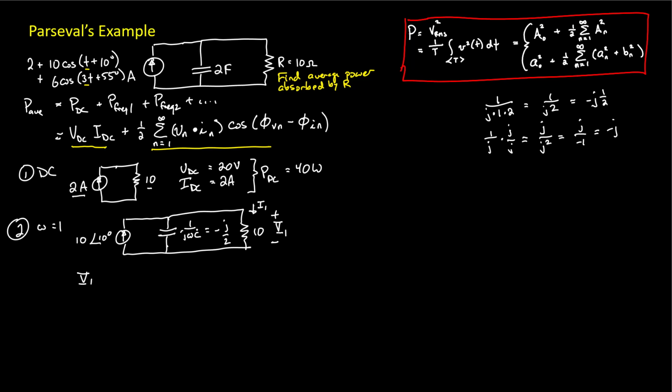Of course, that would give us I as a result, and we're really looking for V. We could do a nodal. We'd have, put ground down below, one equation, one unknown. I think it's even easier, though, to say that the voltage across this element is the same as the voltage across both elements. So to find that voltage, we can find its equivalent impedance of that capacitor in series with that resistance, and we're not going to change the voltage across it.